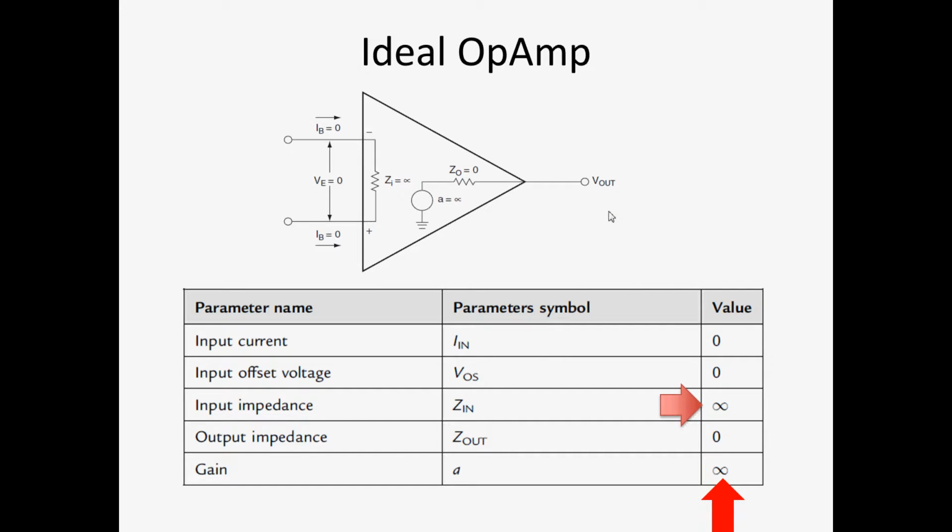Anyway, the ideal op-amp, or operational amplifier, as I said, has an infinite impedance. So all the amplifiers that you're going to use are voltage amplifiers. Now, how do you measure a voltage? You measure a voltage by putting something in parallel to the voltage you want to measure.